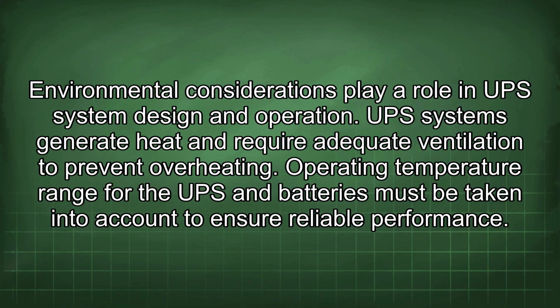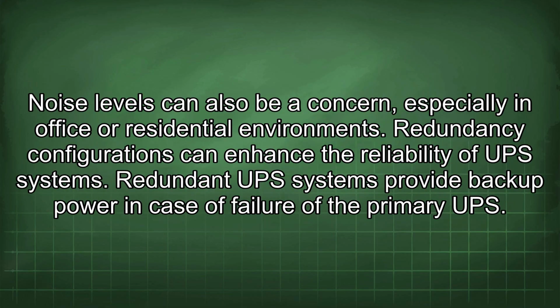Environmental considerations play a role in UPS system design and operation. UPS systems generate heat and require adequate ventilation to prevent overheating. Operating temperature range for the UPS and batteries must be taken into account to ensure reliable performance. Noise levels can also be a concern, especially in office or residential environments.